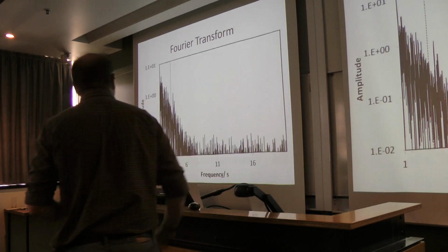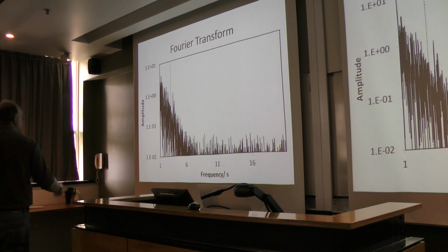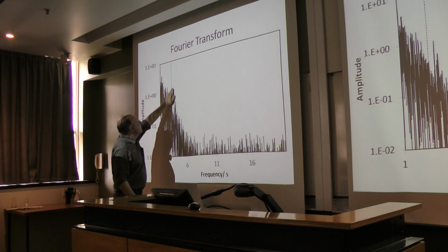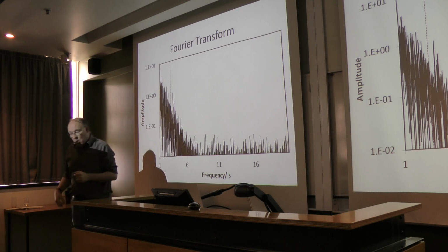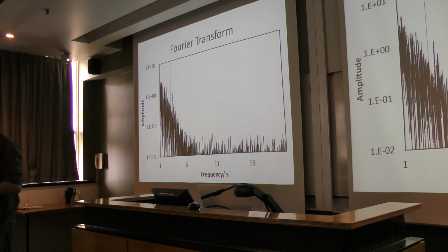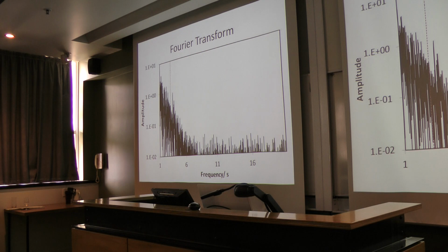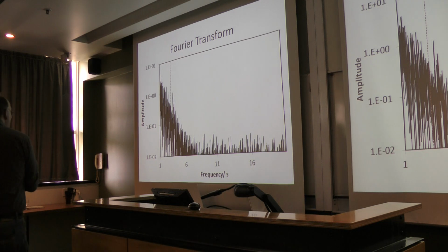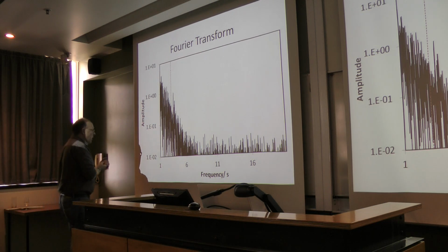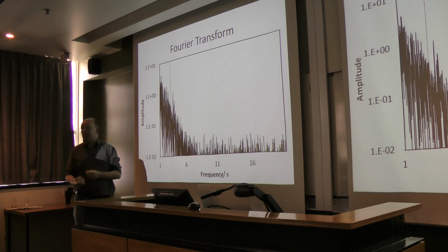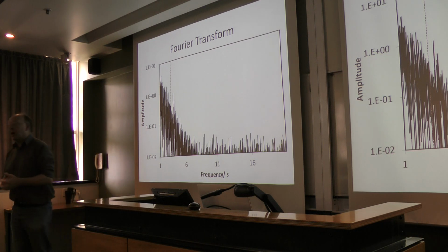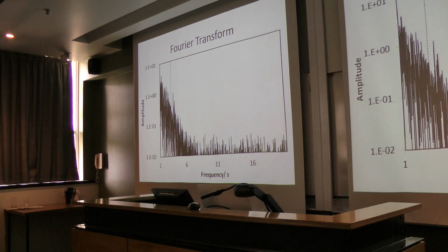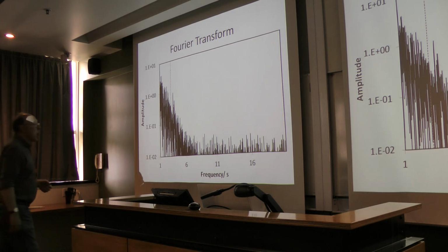If I go down to 1 to 20 Hertz, then I have this line on here because there's a correlation. I haven't measured the flame flicker because that involves getting the video out and doing a frame-by-frame analysis of it, which I might ask a student to do, actually, because I don't want to do it. But I have a correlation, and I don't know how accurate the correlation is, I'm going to have to dig a little bit deeper into that, which says I should expect a frequency of about 3.2 Hertz.